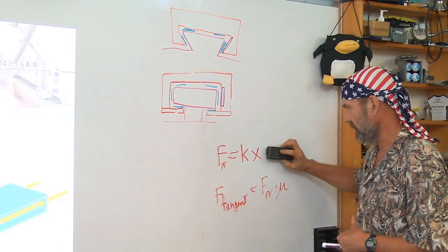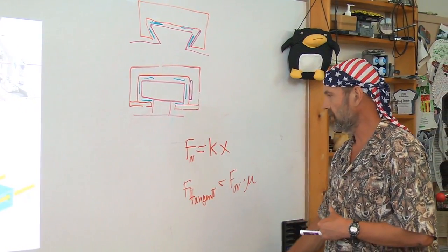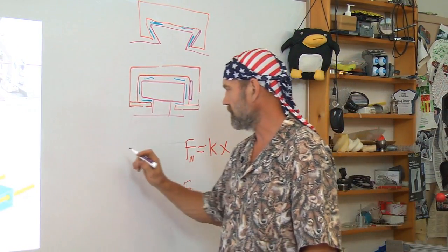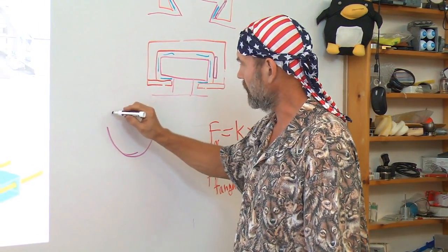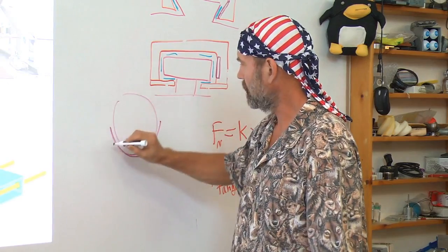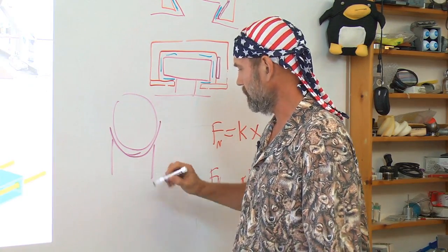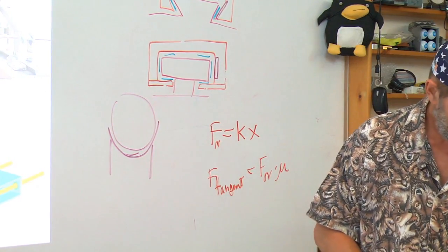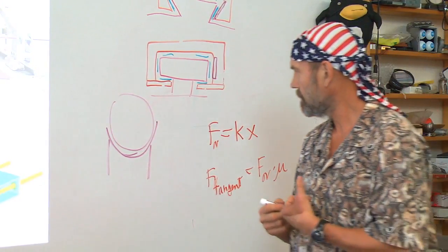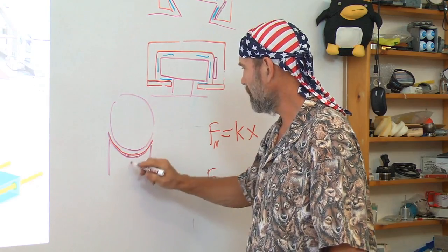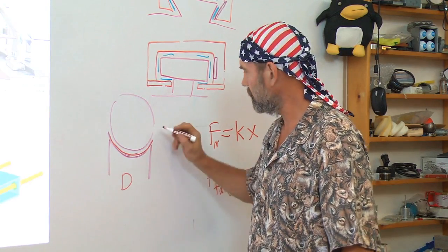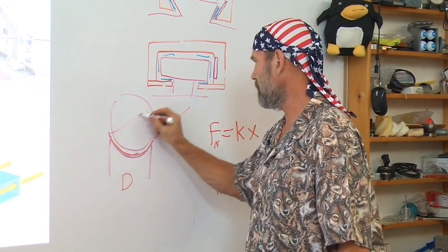Primary contact point issue is they're very stiff. Analysis issue to be focused on is: what is the actual projected contact area for the bearing? Is it across the diameter of the shaft? And there's a certain length.